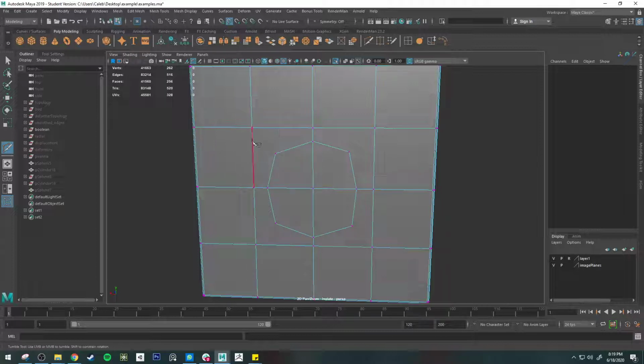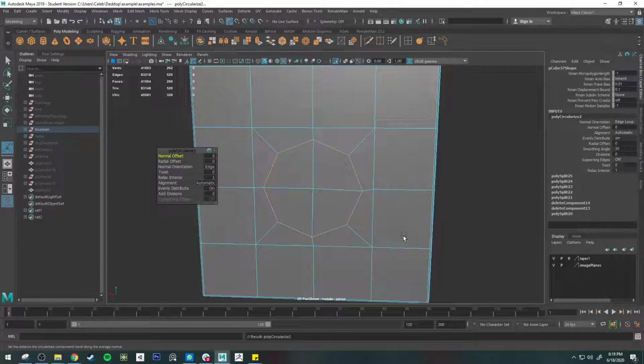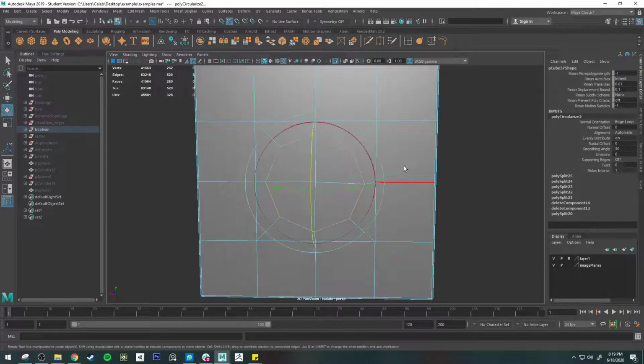I have n-gons 1, 2, 3, 4, 5, 6 here. So I'm just going to cut that corner. So it's 2 quads, 2 quads, 2 quads, and 2 quads, right? So now I have this edge ring, this edge flow direction that is right here, right? And so I made a radial edge flow direction, right? And I'll probably grab these guys and clean that up. I definitely wouldn't do it this way, but I could use circularize to kind of smooth it out and make it nicer.